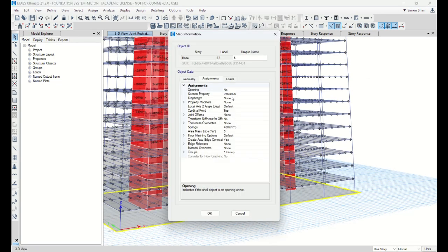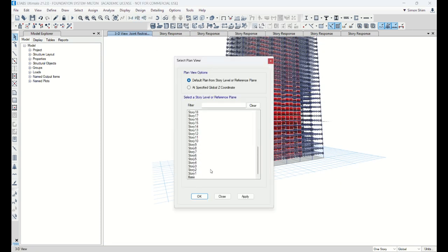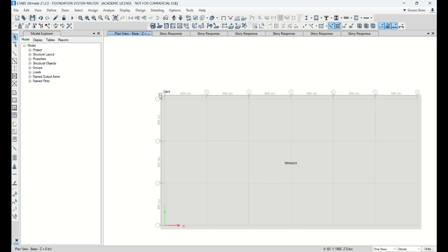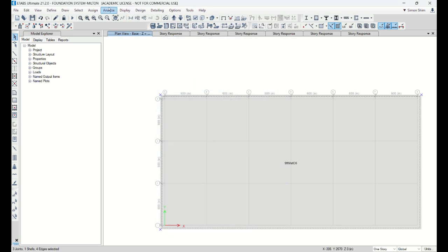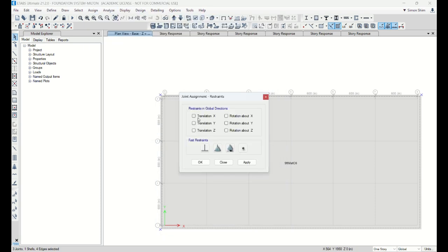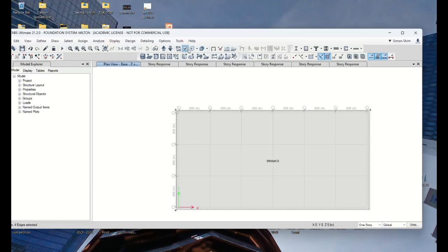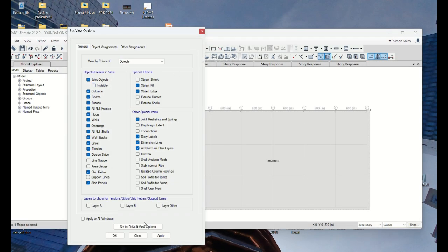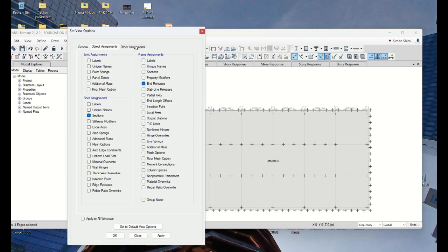So this mat also has a spring constant, so there is a vertical stiffness. Okay, I'm gonna put this one in the X direction. Do we have an XY restraint? I'm not sure we have it. No, not yet. So I'm gonna assign it, otherwise this model is gonna move in X and Y. Somehow I cannot clearly see where my restraints are.